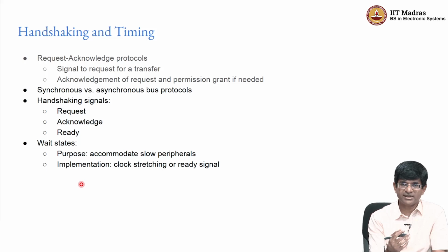It just asserts a signal that says, wait, the data is not yet ready, and the CPU either needs to just wait, or in some cases the CPU can go ahead and do something else and will get alerted when the data is actually present and can be read back. Right? The point is, this is effectively a form of handshaking. It allows two different peripherals that run at different speeds to be able to communicate in both directions.